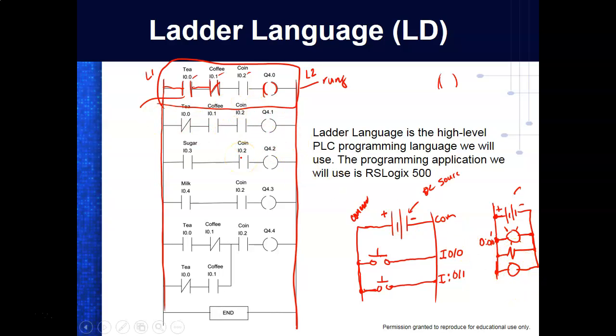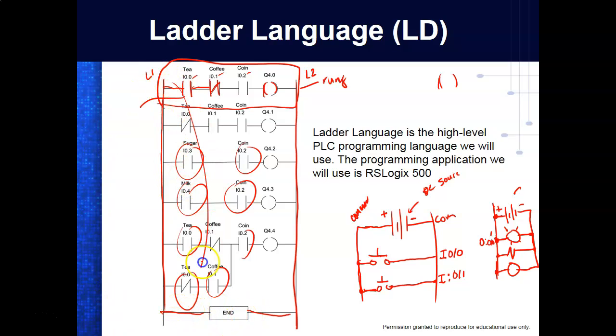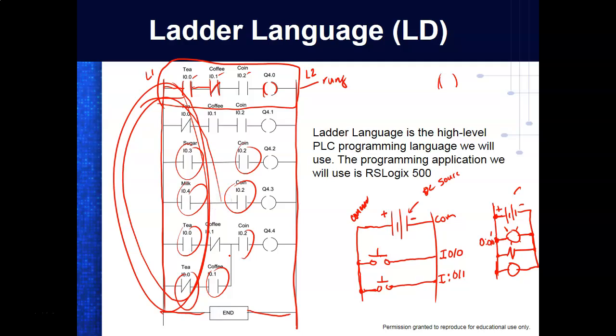Inside here, we've got very few symbols. We've got inputs, we've got contacts, and all these inputs are being controlled by something hooked up to a port. But we'll show you all that. And then we'll have an end rung. The end rung tells the program to come up here and just loop. So this program is constantly looping. We call it a scan. But ladder diagrams, we just draw circuits using these symbols, and these will be the only symbols that we start off with.